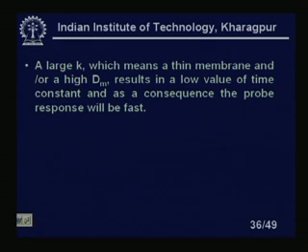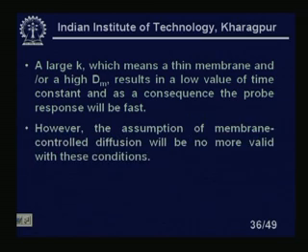A large k, which means the membrane is thin and the diffusivity for the membrane is high, results in a low value of the time constant. So, this will make the time constant low and, as a consequence, the probe response will be very fast. However, the assumptions of the membrane controlled diffusion will no more be valid in these conditions.